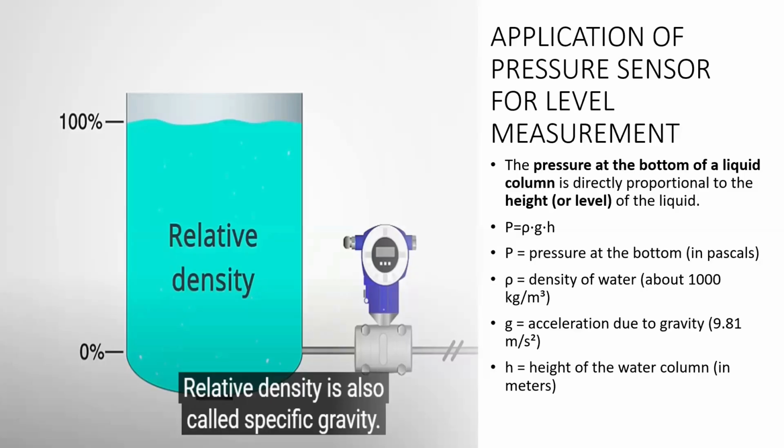Another thing that can affect it is mounting errors. If not properly mounted, there can be bubbles or height error. And remember, like I said, it must be mounted very close to the base of the vessel. Venting also: if you are using it for level measurement, you must ensure that the tank has an open end. It has a vent so as to avoid pressure build-up.